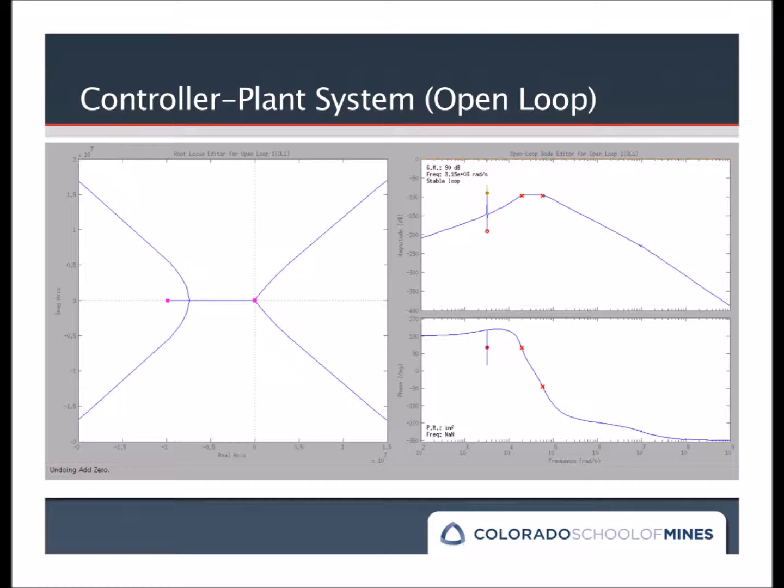The first step was to place a pair of complex zeros at the resonant frequency. This accomplished two things. The first was that it decreased the amount of resonance seen in the system. The second thing that this does is increase the slope of the magnitude Bode plot, which further attenuates any signals below our 4 kHz threshold.